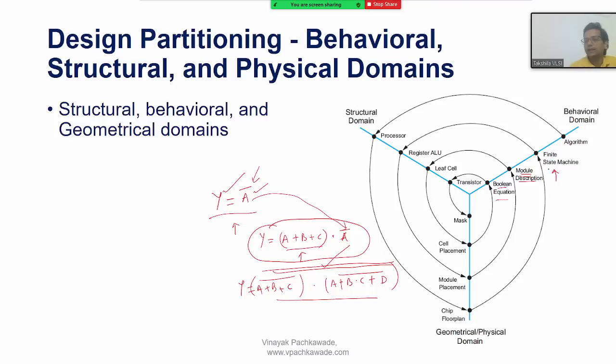This is called a finite state machine. So I define the states A, B and C in the digital logic, and then I say that, okay, if the input is 1 or 0, then this state is connected, jump to this state for 1 or 0 or something like that, right? So this is basically called a finite state machine. In digital logic design, they also use this, but generally this is not used anymore. They basically just do the RTL coding nowadays.